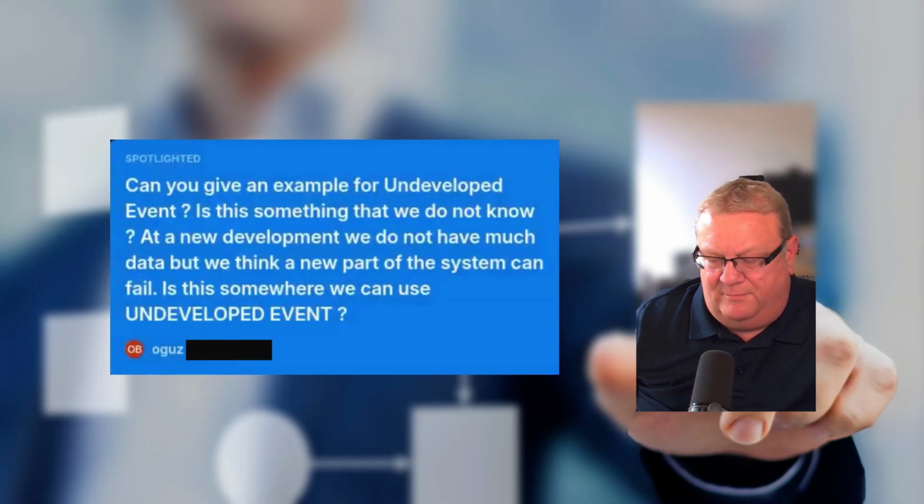Obviously, it's never going to be 100% accurate, but you can get an idea of temperature in a certain season. And then you're not going to develop that event in the fault tree. So rather than building all the events below it that might lead to there being high ambient temperature, you just say this is an undeveloped event we're going to include for this in the fault tree.